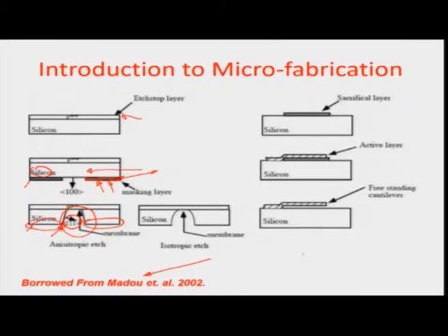So, you are covering something with a layer which is otherwise a sacrificial layer, and you are using a window created in that sacrificial layer to do selective etching. So, supposing today you were to etch a very small region, let us say a 100 micron by 100 micron pit is to be created. You can pattern and open up vias in the masking layer in a manner where exposure would be there to the parent material and the etchant would sit on that and start etching. Okay. So, it is a very interesting way of carrying out machining at a very small scale,